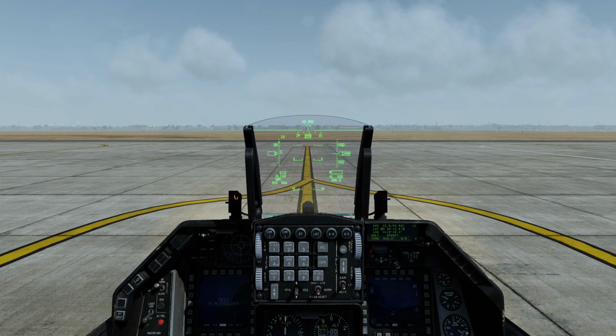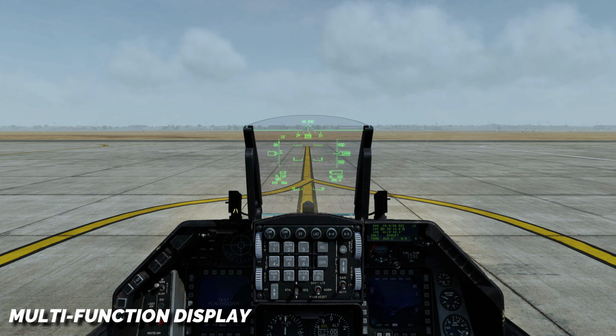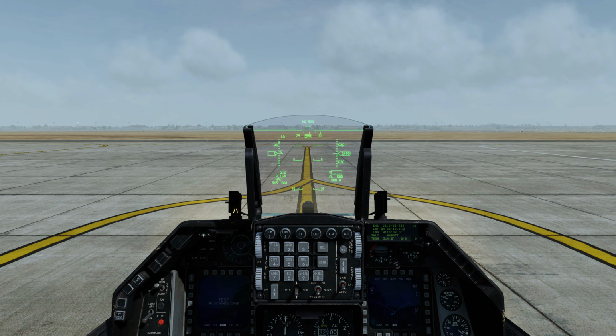To set the avionics as required, the pilot would now place the DTC in the DTC receptacle on the right console. Set the MFDs as desired. The UHF and VHF radios can be set through the DTC presets or manually through the UFC.